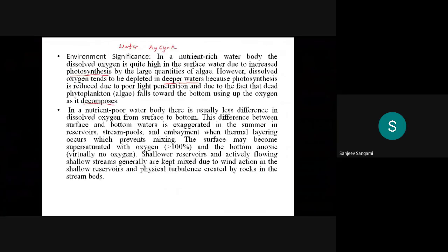This difference between the surface and the bottom waters is exaggerated in the summer in reservoirs, stream pools, and some of the embankments when thermal layering occurs, which prevents the mixing. I already said that the link between DO and temperature is inverse; they are inversely proportional.